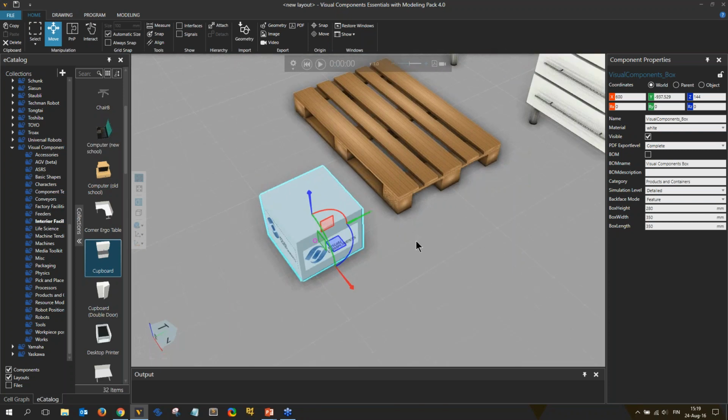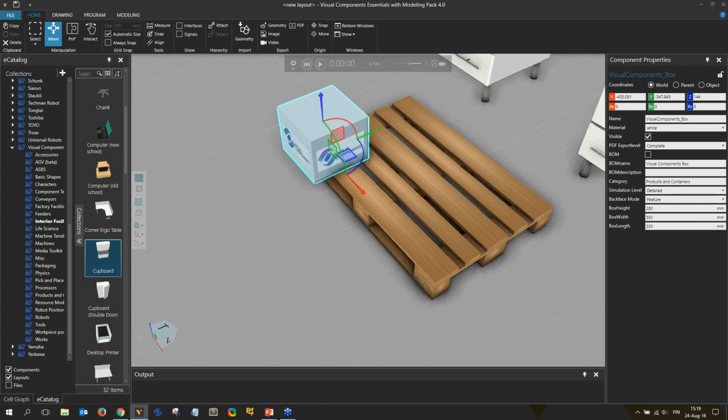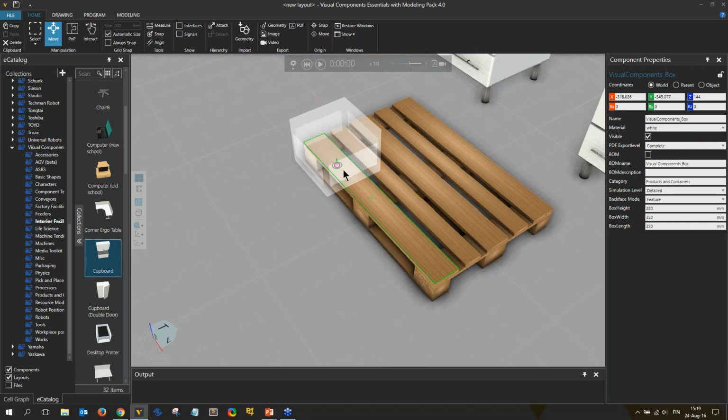And there's also this little donut here. I can start dragging the component from there. If I go on top of another component, it starts to snap on the face, on the center of the face, on the edge, on the middle point of the edge, or on the end point of an edge. Also circle centers are found, but in this model we don't have any circles. And it also takes the orientation from that face.